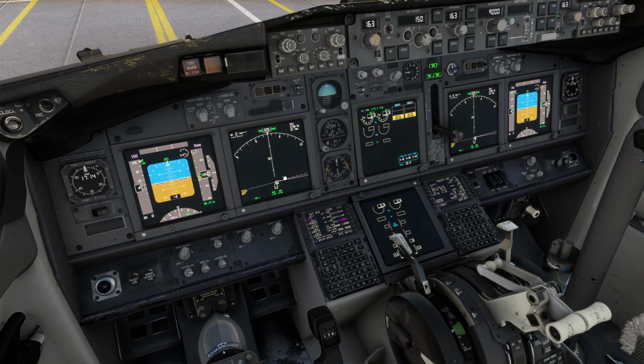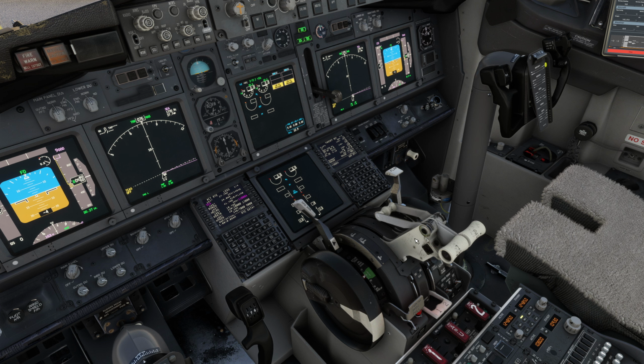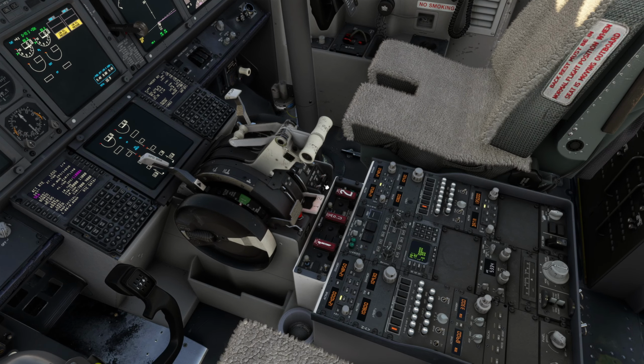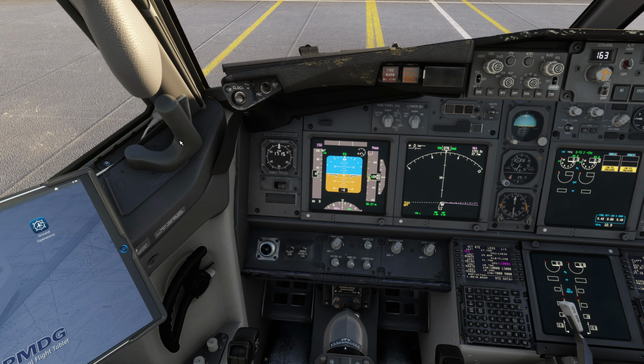Warning annunciator lights, checked. Speed brake, down. Takeoff warning, checked and throttles closed. Engine start levers, cut off. Stab trim cutout switches, normal. Fire warning, checked. Radios and transponder, set. Radar, off. Rudder and aileron trim, free and set to 0. Parking brake, set. Windows, closed and locked, left and right.